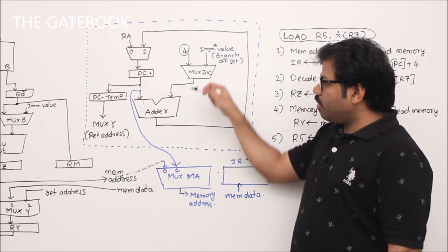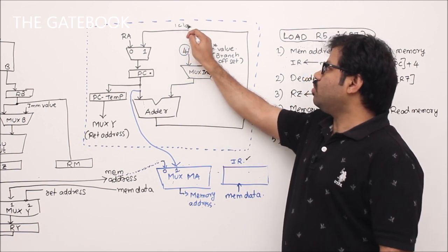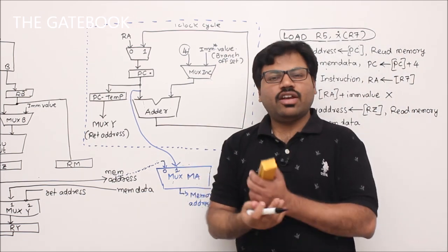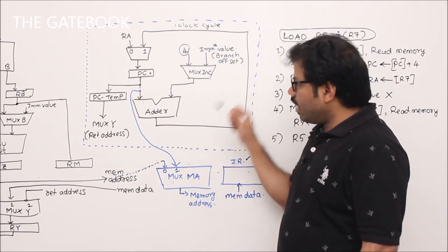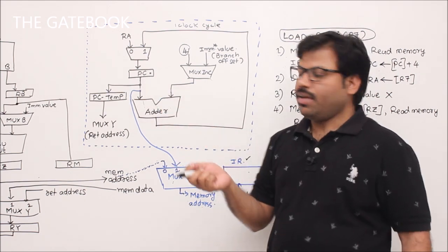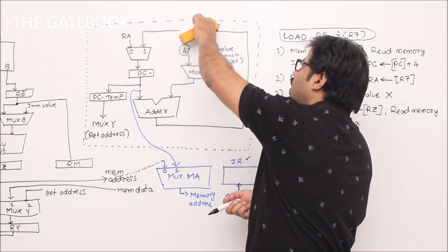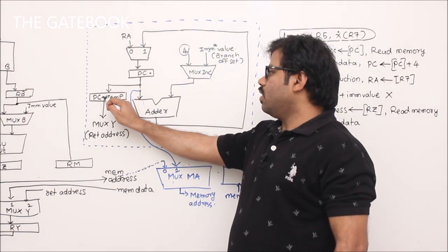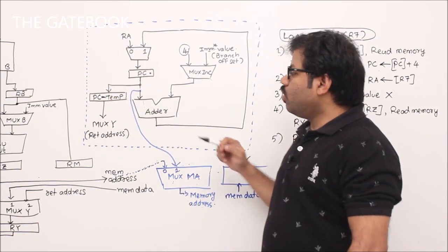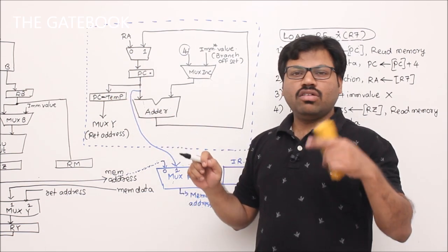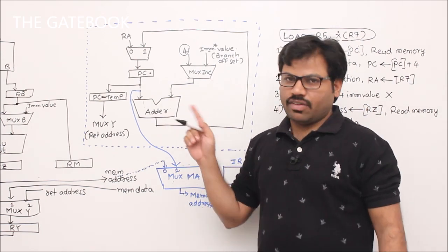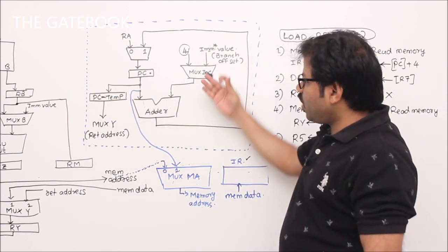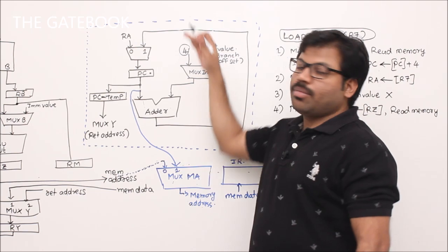Okay. So this circuit can be designed so that within one clock cycle, assume that let's say we are using only one clock cycle to get the value stabilized, the program counter can be incremented. You don't require much time. Now, sir, what is this PC temp? I will explain that later, because it will be good to understand this PC temp with the call instruction. Forget about this. If there is no such kind of thing and there is no immediate value, simply program counter will be incremented by 4, correct?